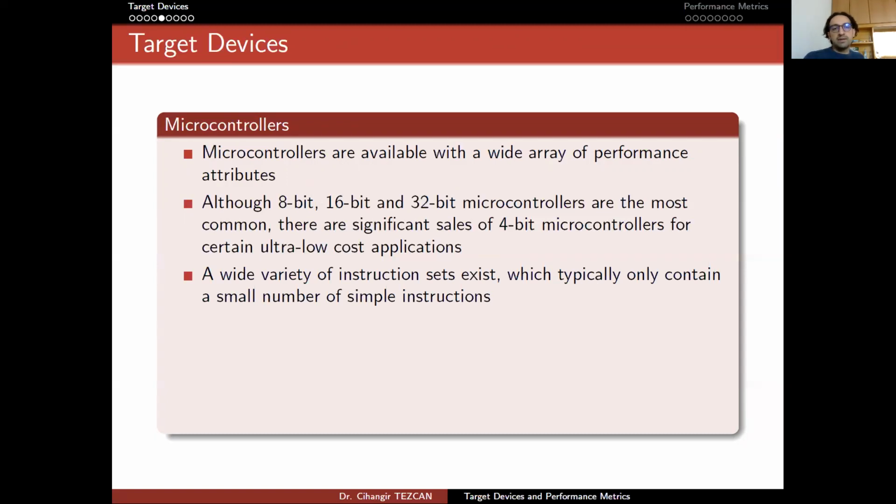Not every device, not every CPU, not every microcontroller has the same set of instructions. Even with high-end computers, some CPUs or GPUs might have an instruction for rotation, so you can rotate bits of, for instance, a 32 or 64-bit word with a single instruction, but some CPUs won't support this instruction, so you have to use 2 shifts and then an OR operation to perform the rotation.